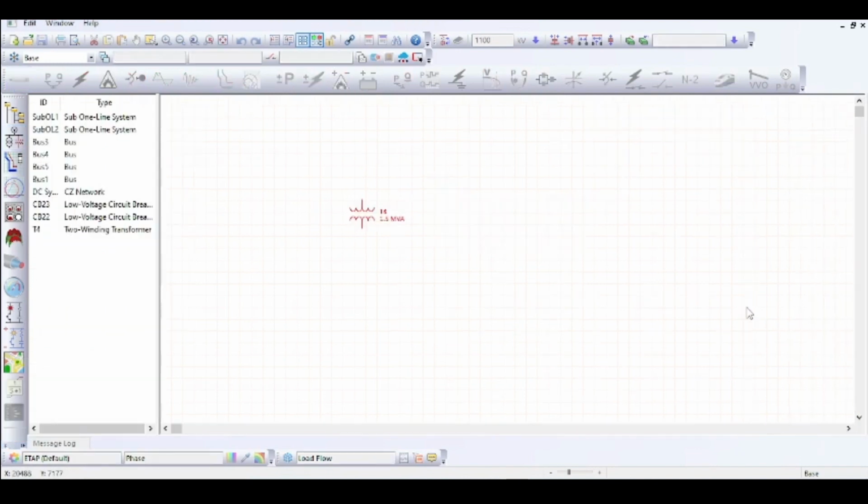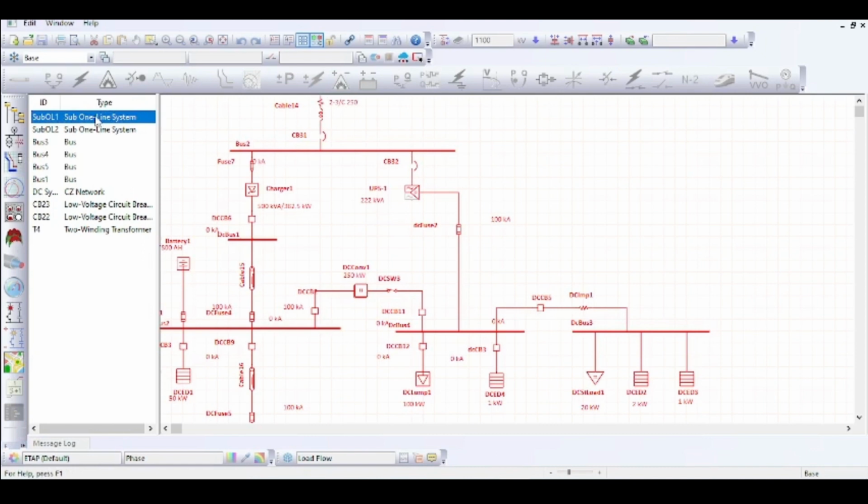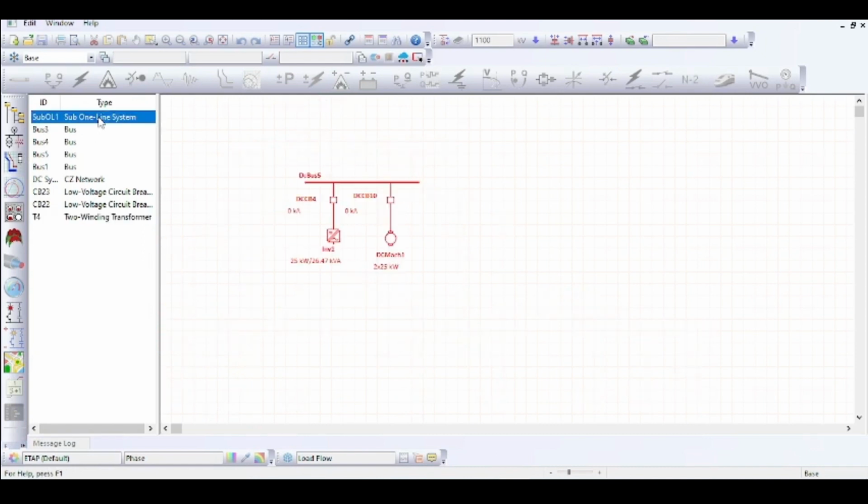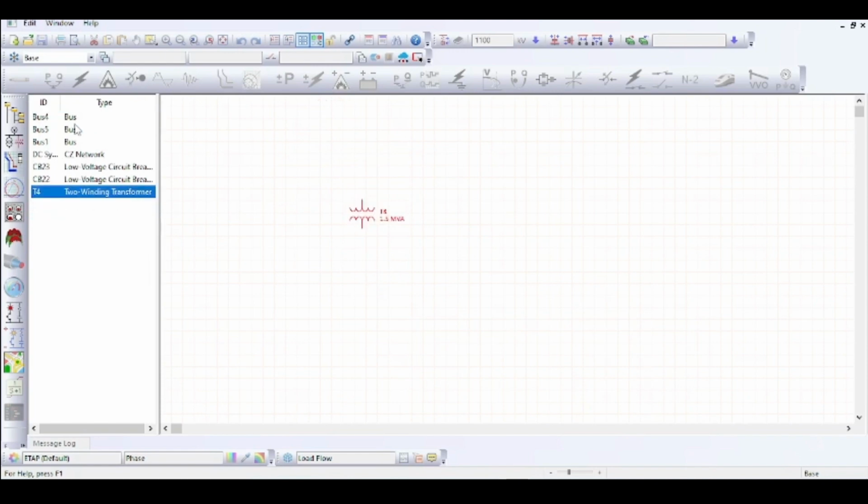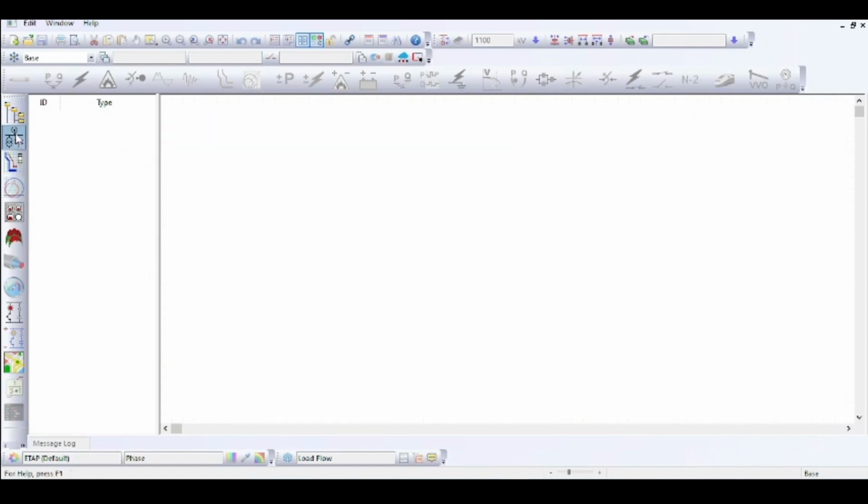So the components that we are deleting, from this edit case, will come inside the system dumpster. So whenever we want to continue the modeling, we have to delete the components in the dumpster, or else the naming will give confusion.